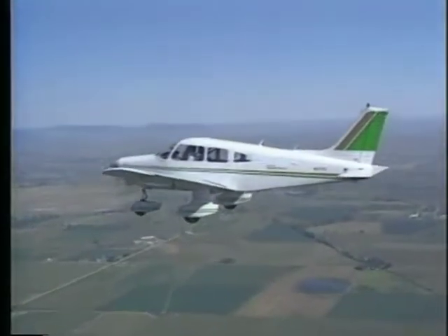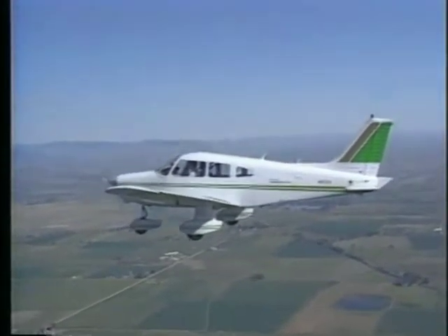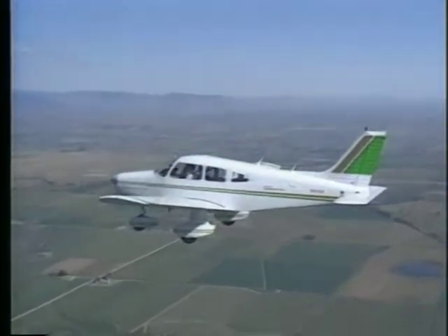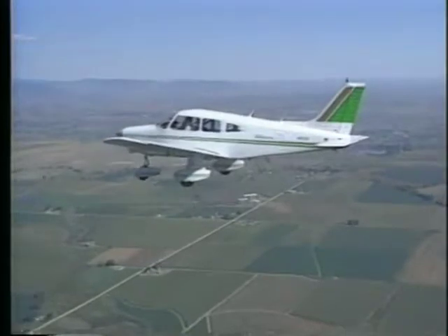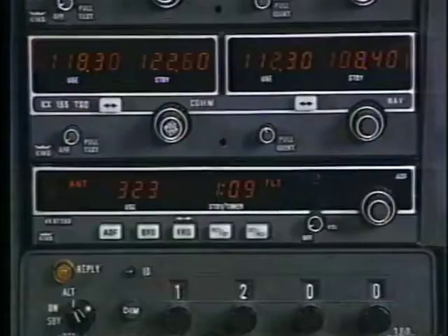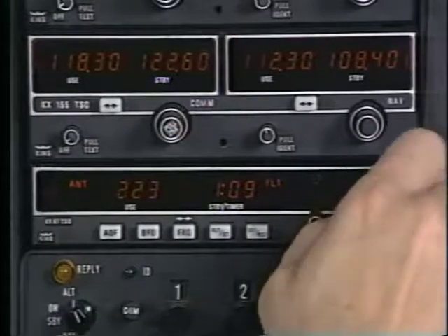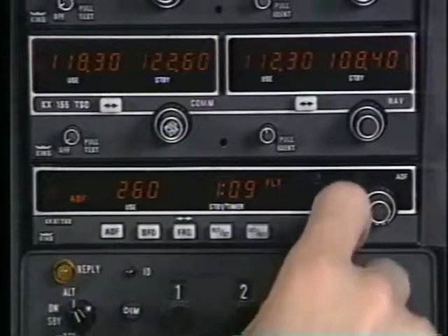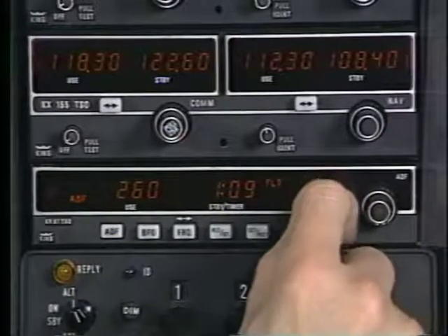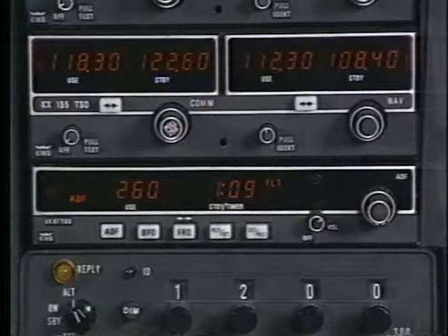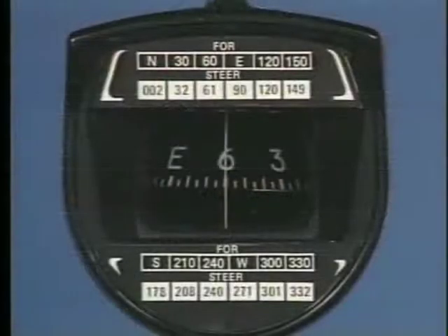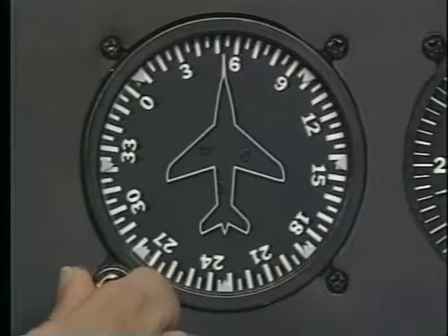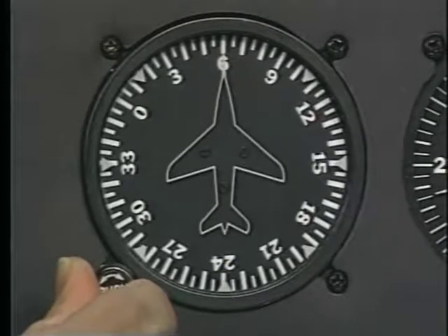Sometimes, when using ADF, the signal you receive may be erroneous or unreliable. If you are familiar with some of the limitations of this instrument, you may be able to avoid or minimize errors you might encounter. For example, reception capabilities for ADF facilities can vary considerably. To be sure you're receiving reliable information, always identify the station before use, then monitor its ident feature. If your heading indicator is not properly set to the magnetic compass, you may have problems with tracking and intercepting procedures. You should monitor these instruments often to ensure that the heading indicator has not precessed.